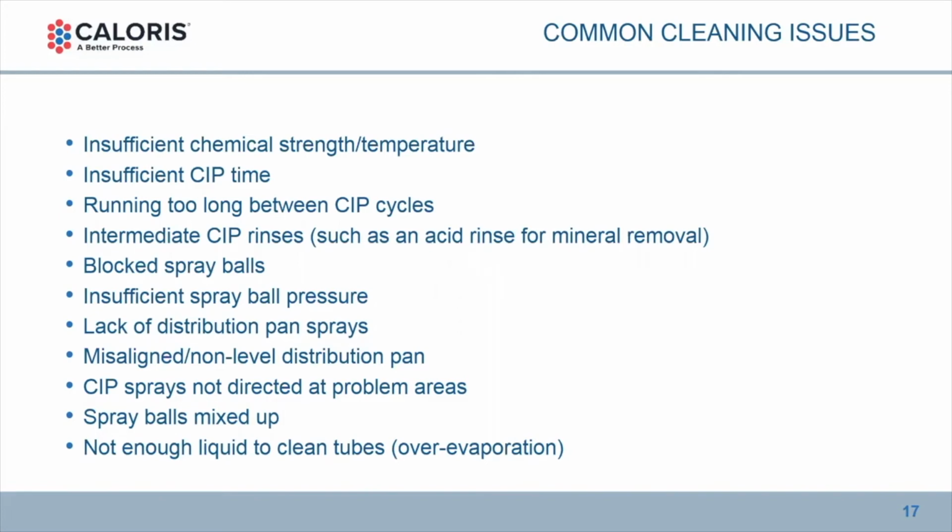Block spray balls, insufficient spray patterns in the distribution pan, as we talked about before. Is it misaligned or is it not level? We've seen both of these in evaporators over the years. And in either of those cases, you are not properly distributing and keeping your tubes wetted.